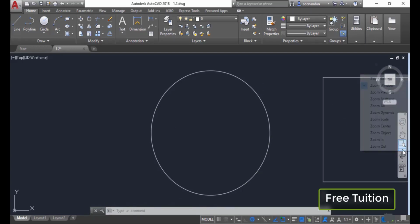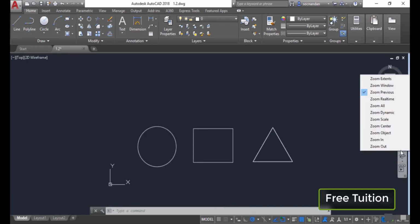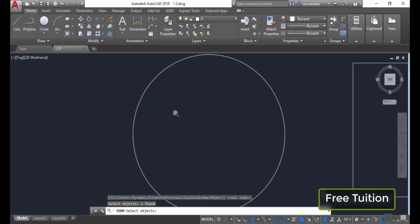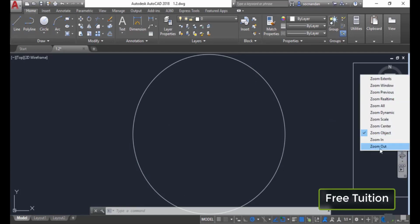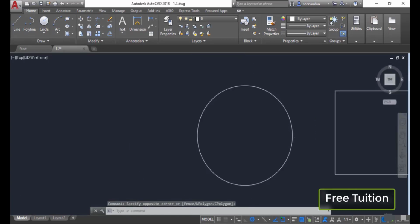We also have zoom previous, that will return to the previous state of zoom. And also this zoom object option. Select zoom object, click on the object, and that object will be brought in the complete area of the drawing. In a similar way, you can access all of these options according to the requirement of a specific drawing.